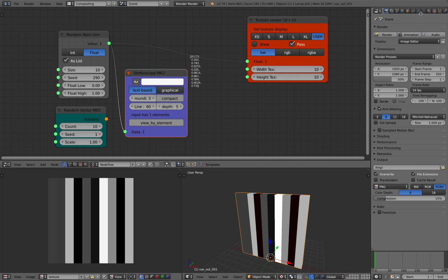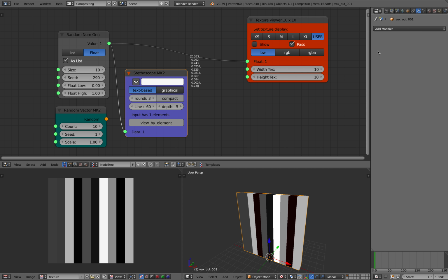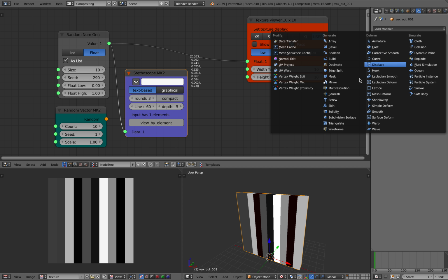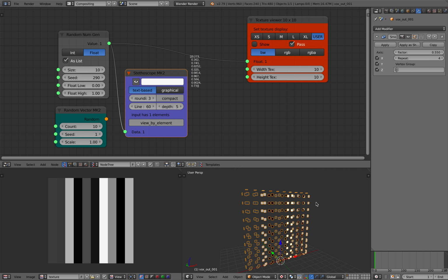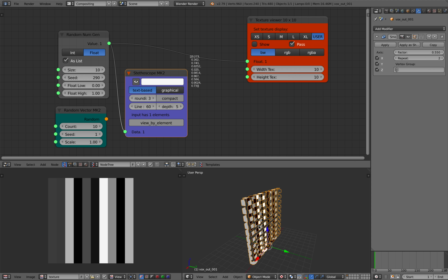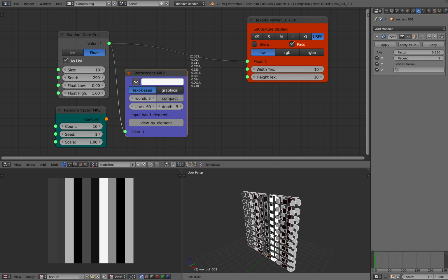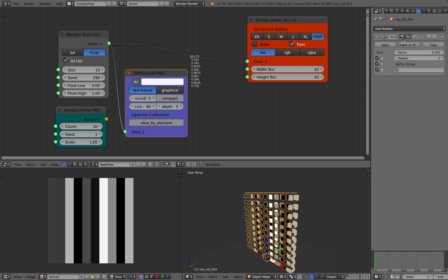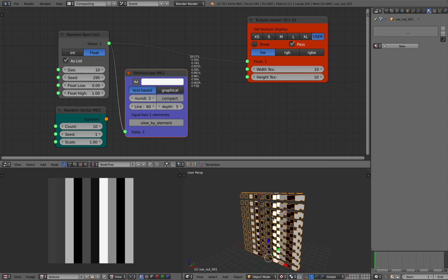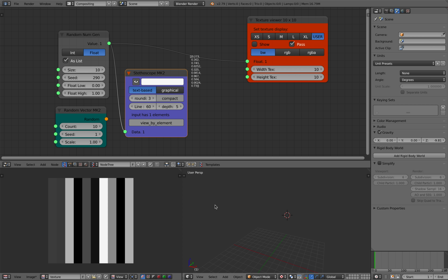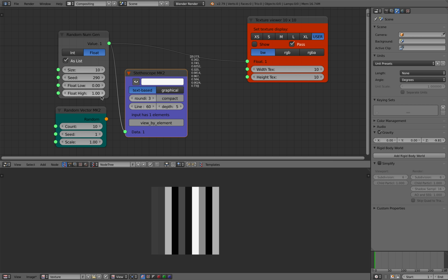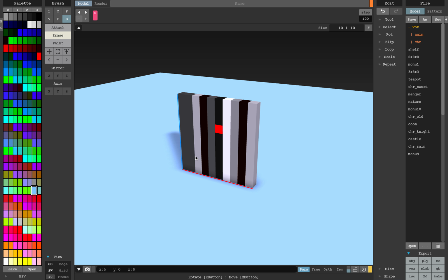With this, be careful because the PLY doesn't export per block. If you try to smooth it or something, you will start to see that they are all just separate polygon faces. Keep that in mind, and if you separate all of them, it's going to be very heavy. So let's delete that. The color itself is not a material, it's basically a vertex color. So let's go back to this and see if we can generate something more interesting.